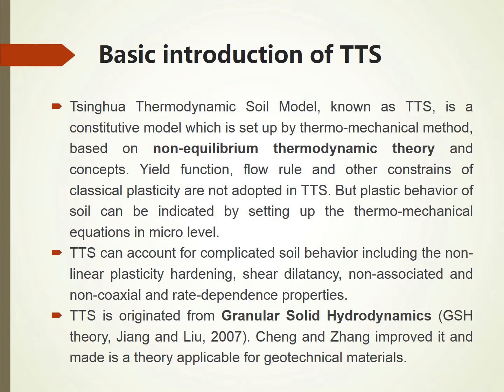And TTS can account for complicated soil behavior, including nonlinear plasticity hardening, shear dilatancy, non-associated and non-coaxial, and rate dependence properties. TTS originated from GSH theory.